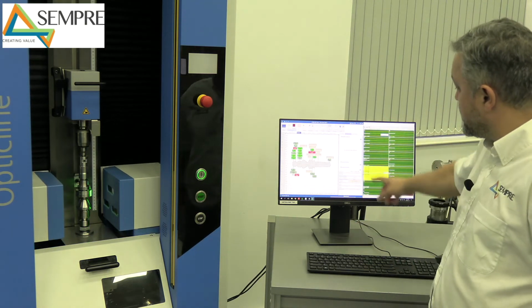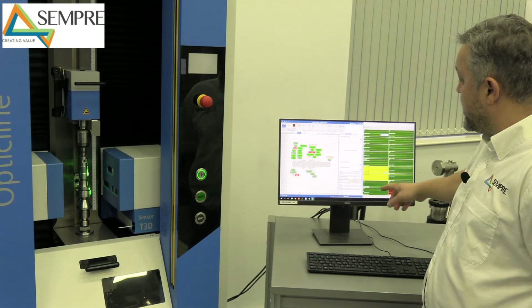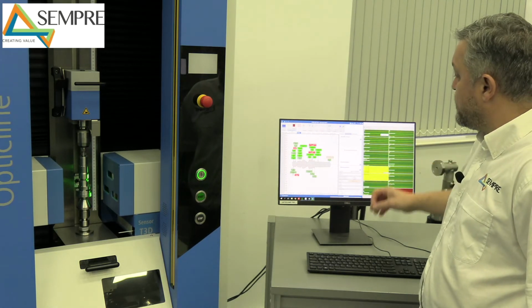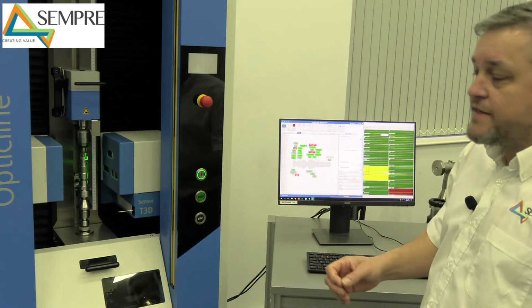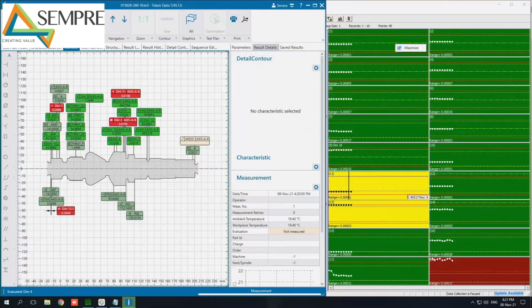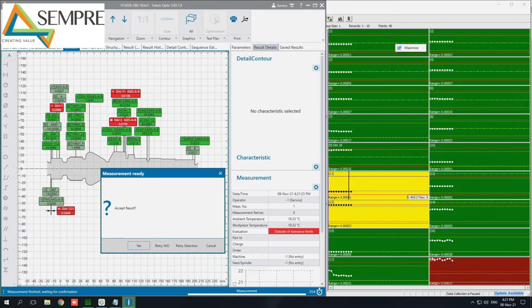We also have on the right hand side another display here, which is actually an application that will analyze data and harvest data, but again it will do it very quickly and efficiently and tell you whether your process is capable for it, so calculations like CP, PPK, etc. Very quickly now we've actually completed the measurement routine. So what we're going to do then is absorb the data and automate that process of the data directly from the machine straight back into the HighQA software.